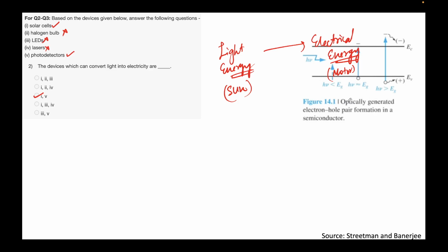That's a technical term. Essentially, you are just breaking the bond, and the electron will now jump to the conduction band, the hole is left behind, so an electron-hole pair is being generated. Okay, now we'll do the opposite, which is to convert electricity to light.